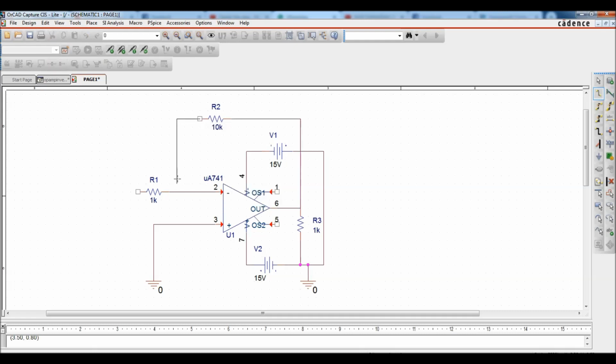6. Okay, right. Now you need to make sure that there is no node here. You just drag it so that it will pass this portion of your circuit, because if you stop here you will have this node, and that is wrong because this is directly connected to 6. So you need to be careful when you connect this kind of circuit. Okay, so I think that's done.